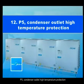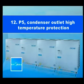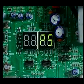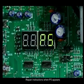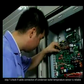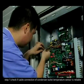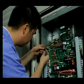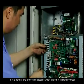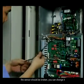P5. Condenser outlet high temperature protection. Repair instructions when P5 appears. Step 1. Check if cable connection of condenser outlet temperature sensor is reliable. If it is normal and protection happens when system is in standby mode, the sensor should be broken. You can change it.